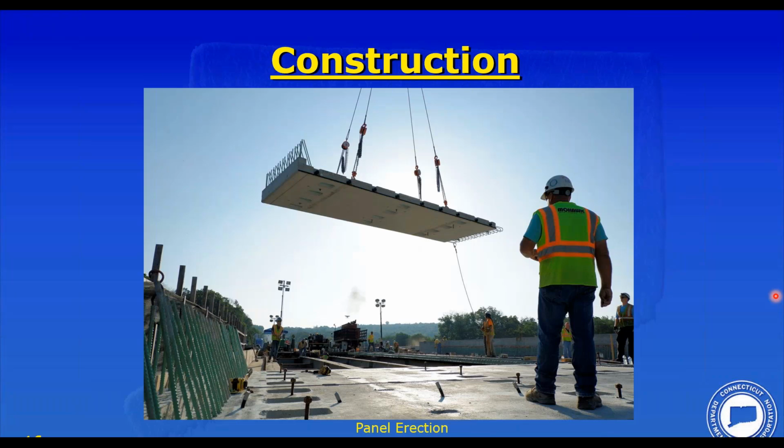So let's look at some pictures of construction. We got some nice shots here. This bridge was completed not too long ago, showing the erection of the deck panels. These are very similar to the deck panels that were shown in the first presentation, where we have a longitudinal post tensioning, blockouts for shear connectors, and leveling bolts. So here we are 30 years later, we're using the same details because they work.